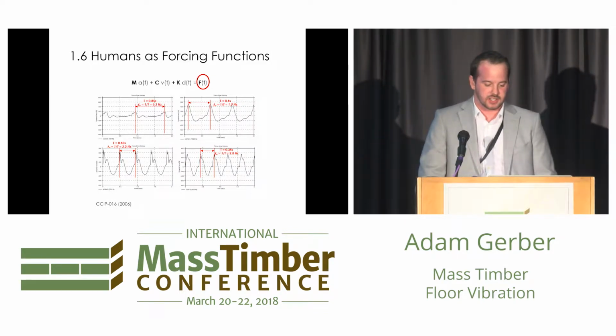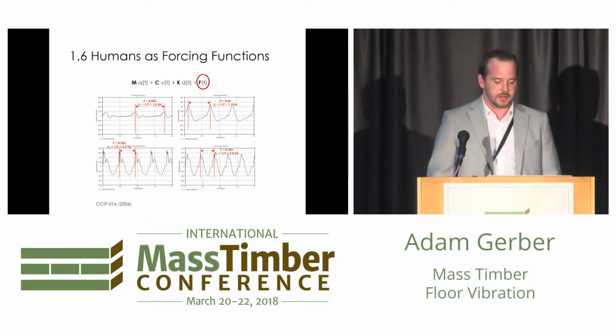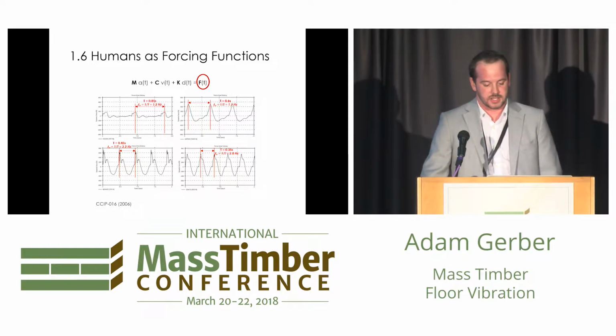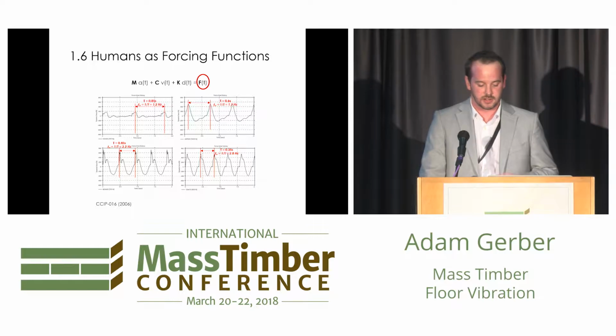So the last part of the equation is the forcing function. And so just a quick look at what it means when we say humans are imposing periodic loads on a structure. So here we have a few different time histories of people walking, where they measured the rate of walking and the force that they were imparting on the floor.